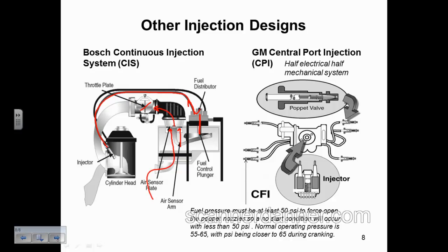They started this in like the 40s, I think. It's the first fuel injected system, and actually it was very efficient. What they did, if it's spraying all the time, is it took 720 degrees of crankshaft rotation to have the right amount of fuel in this area. That's how small the spray was.